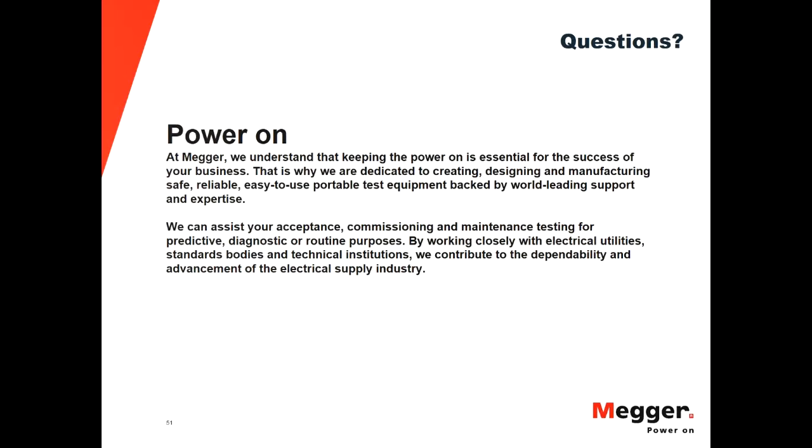So most of the failure modes that can be detected in the lead-acid batteries, because the active material, the lead, is dissolving into the electrolyte and changing the ohmic value, are not going to be detected that easily in the nickel-cadmium batteries. There are a few failure modes in nickel-cadmium batteries that will definitely affect the ohmic value of the cell, but there are not going to be many of them.